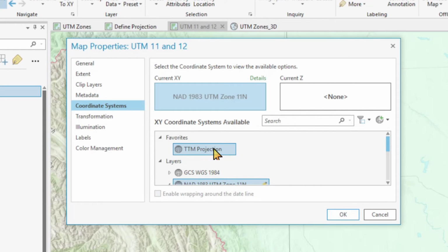The last comment I want to make is, once you have created your own projection, you have not really saved the projection. You want to basically take the projection that you have created. In my case here, this 10 TM projection that we just created a minute ago, if you want to make it permanent, you have to right click and say add to favorites, which is something I have already done here. That way that projection is available for other projects.